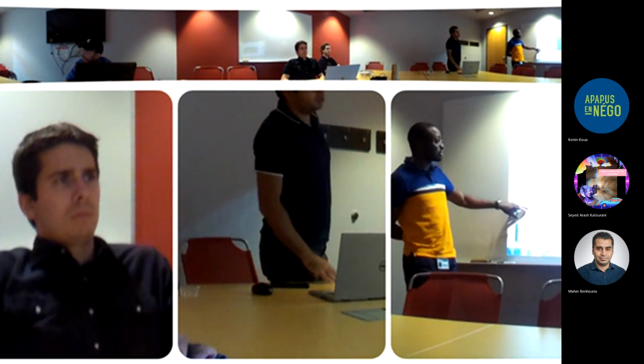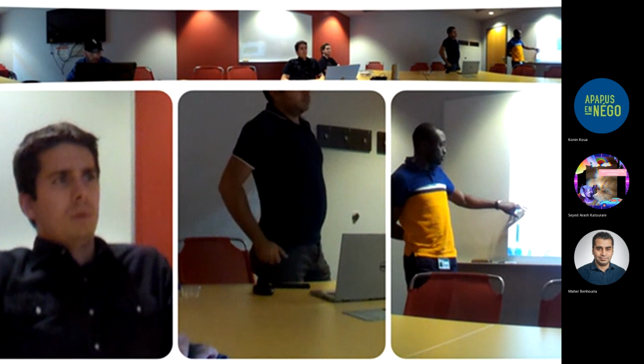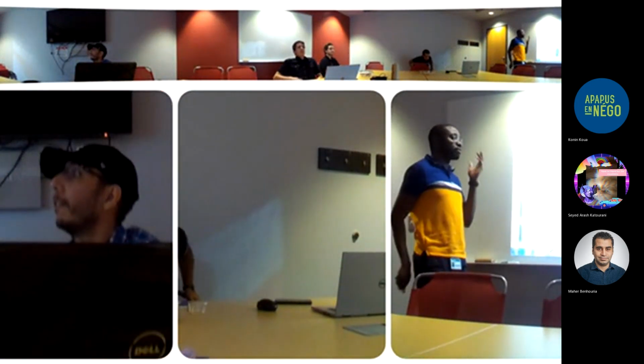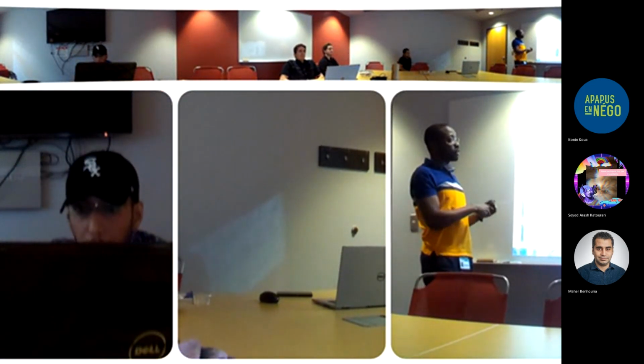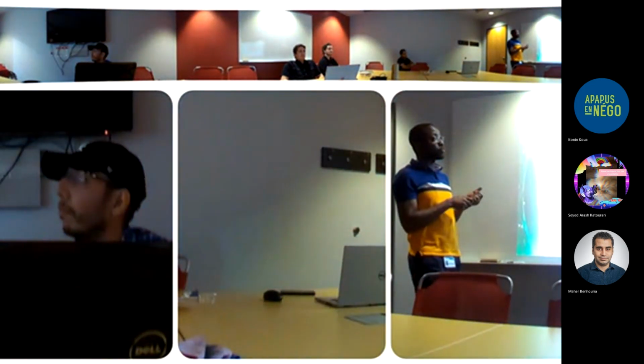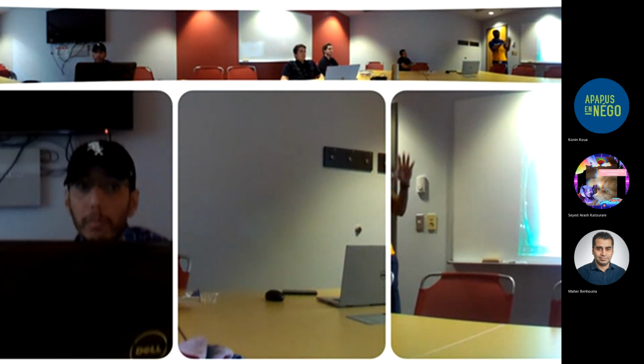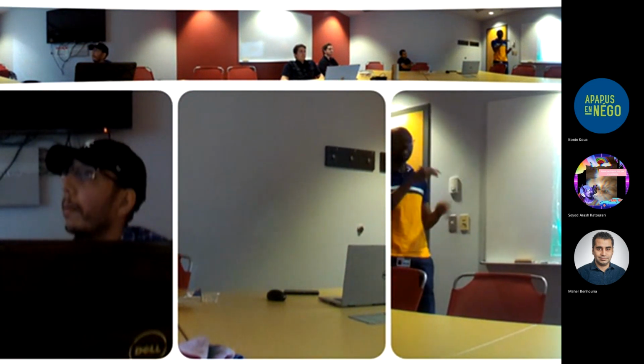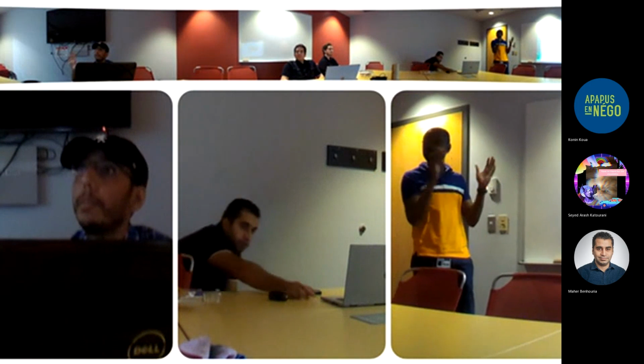If you show this one, the slide 3 here. So the main thing to remember about the layout dependent effects is that when your matching is important, whatever is surrounding your device is important. Both devices need to see exactly the same thing.